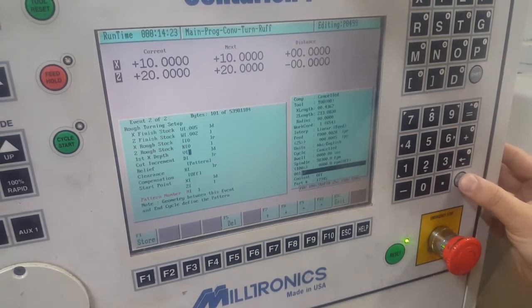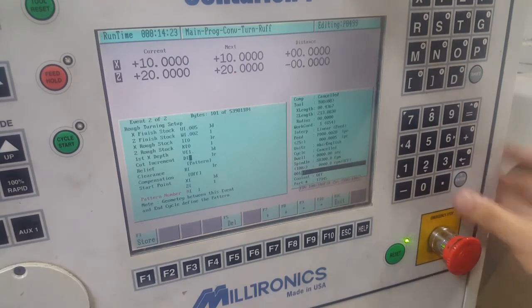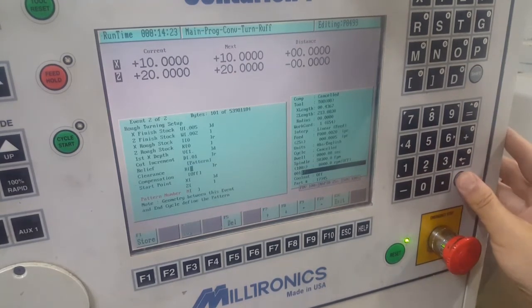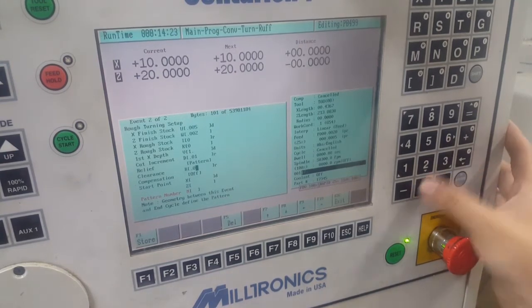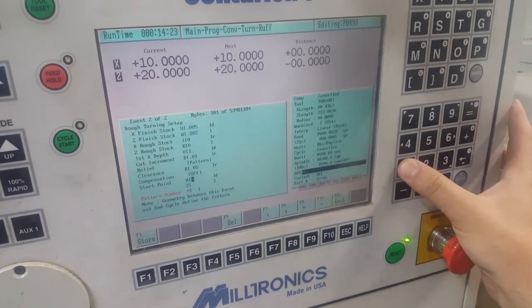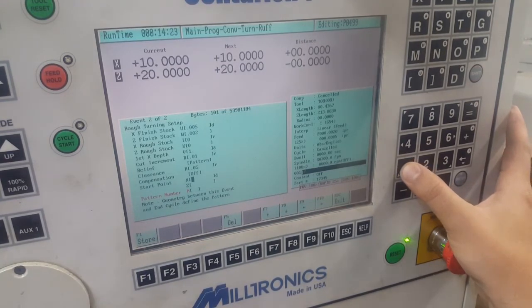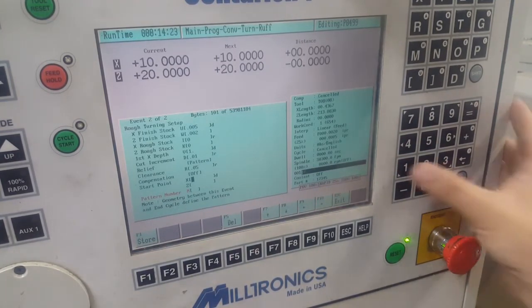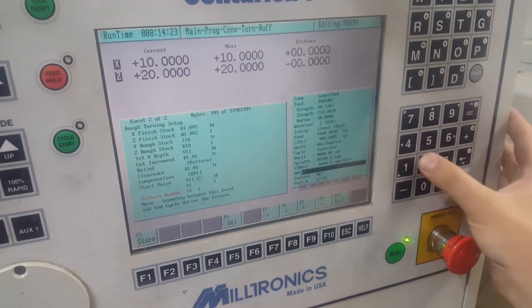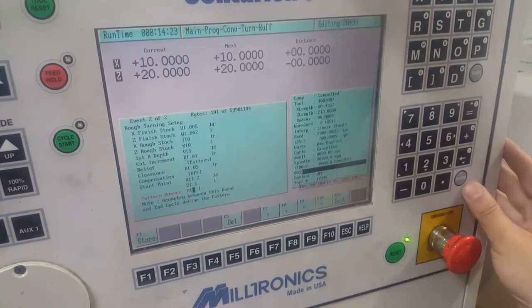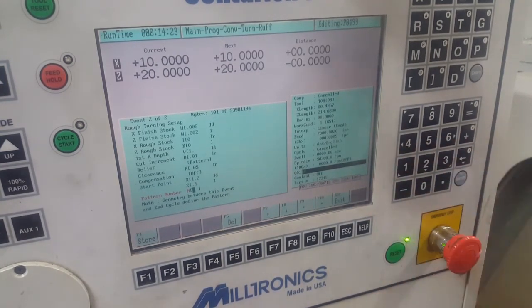First X step for 1 inch material, so I usually just do that 1 inch in case it's oversized or it's got any wobble to it, just do a little cleanup pass. 10 thou cut increment, which will be 20 thou in diameter. Clearance 50 thou. Starting point, again, just anywhere off of your part that'll be greater than any value that you might need to use to lay out the geometry of your part. So 1.2 and 0.1. This is going to be a new program, so we'll be back on pattern number 1.